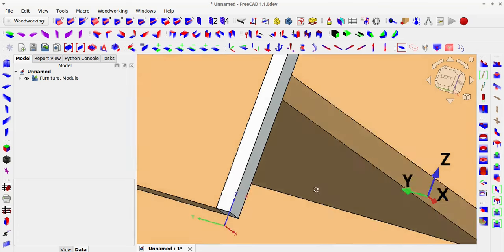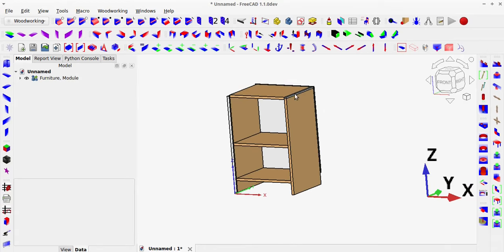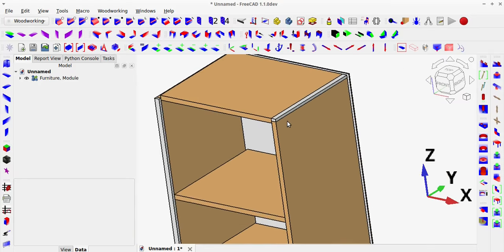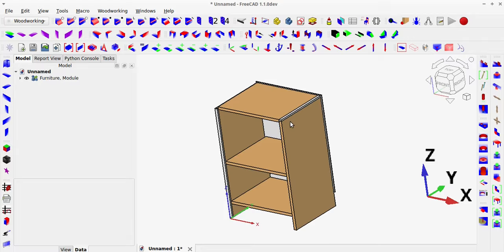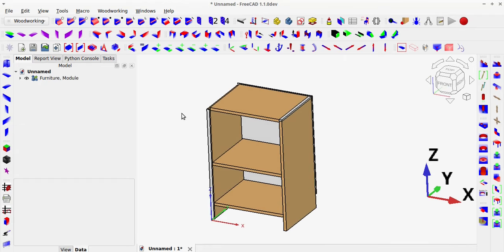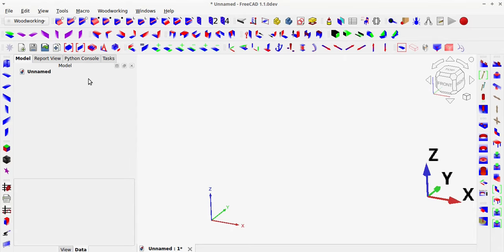In the first case, I selected the visible option, so the entire furniture is spaced from the origin by the thickness of the veneer, and additionally some edges appear lower than others. As you can see, adding veneer achieves a complete fit. If you choose the everywhere option, space for veneer will also be reserved between the shelf and the cabinet sides.